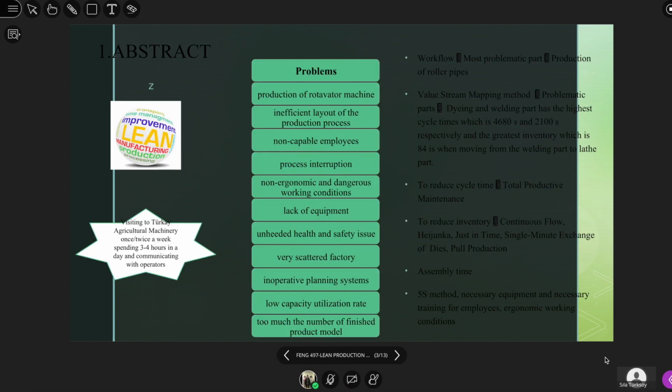Did you do any time studying for the first semester? Yes, we did. Actually, we prepared a value stream map according to our time study. How many observations did you get for the time study to find reliable data? For welding, we did 5 time studies. For dyeing, we only did 2 because it's too long to measure. It depends on the parts actually.